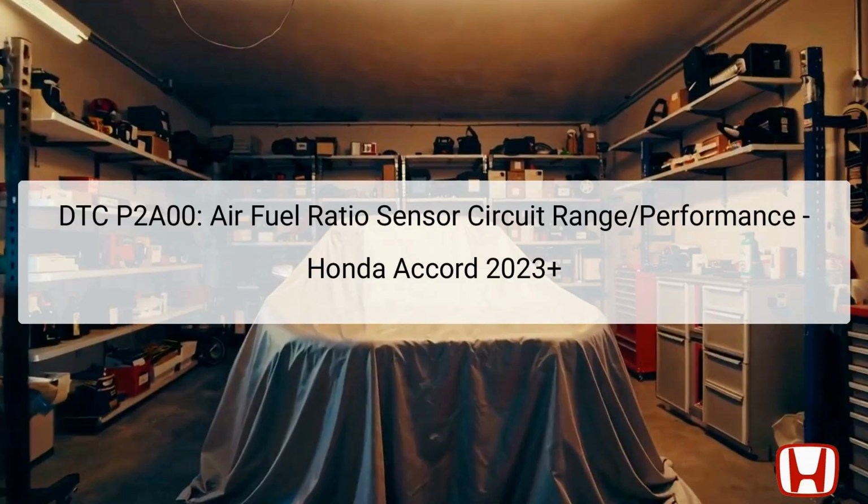The Diagnostic Trouble Code DTC P2A00 indicates an issue with the air-fuel ratio AF sensor, specifically sensor 1. This code is triggered when the output readings of the AF sensor deviate significantly from the expected parameters, affecting engine performance. The AF sensor's primary role is to monitor the oxygen concentration levels in the exhaust gases, ensuring that the engine runs at an optimal air-fuel mixture.